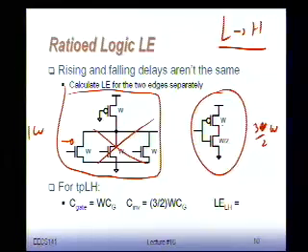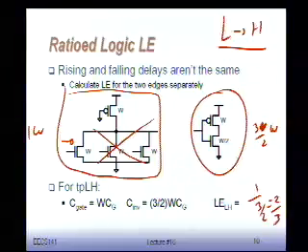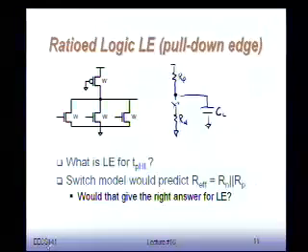Well, it's 1 over 3/2, which is equal to 2/3. So effectively, this gate has a lower logical effort than a CMOS inverter. And that's exactly what we were hoping, right? Otherwise, we wouldn't have done it. So this shows again how you can use the logical effort technique to compare various gate structures.